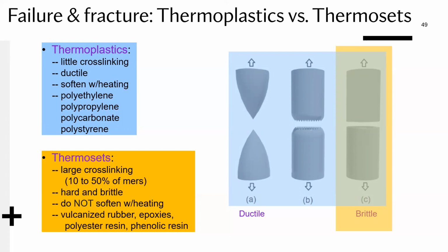So again, in terms of thermoplastics, you can also see the brittle failure mode, but that all depends on temperature. Also depends on the strain rate, as we discussed. So if you actually increase the strain rate, it has the same effect as decreasing temperature. And what can happen is that you can potentially experience that brittle behavior and a different failure mode.